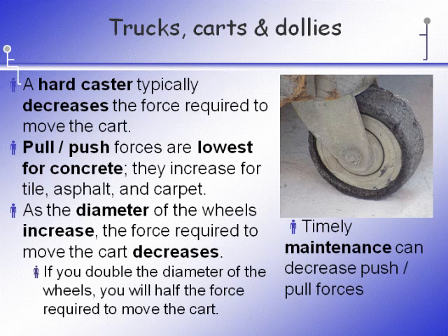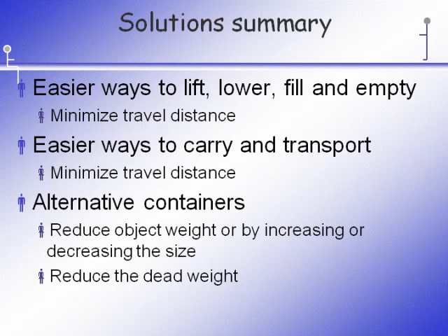And of course, timely maintenance. As you can see here, the last time this caster was changed out is 1968. It is currently 46 years old and can probably use a little bit of maintenance. They don't last forever. And I can't tell you how many different kinds of casters there are out there. Ones for dirty environments, sealed ball bearings, ones that don't have any lubrication in them at all, or can be used in bake ovens where the temperatures get extraordinarily hot. So you can almost always find a wheel to do the job for you.